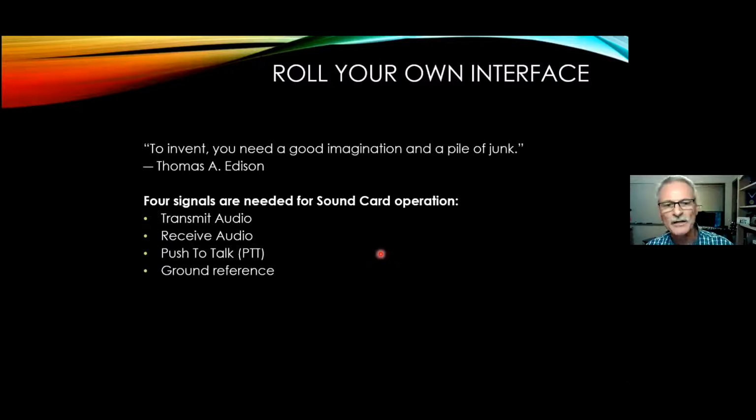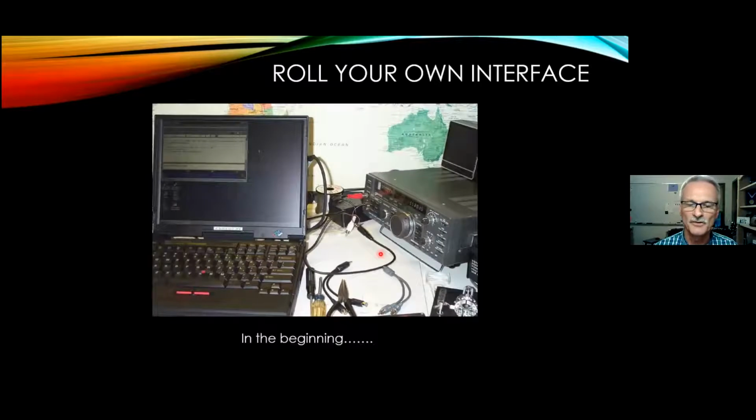Okay, so we're going to need 4 signals from my Soundcard interface going to my radio. Basically, we need transmit audio, we need receive audio, we need a push-to-talk connection, and we need a ground reference for all of those connections. And that's all we need, just those 4 lines, and we can do everything we need to.